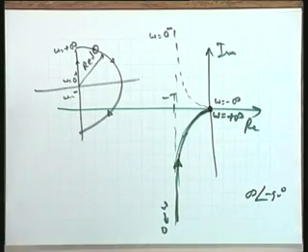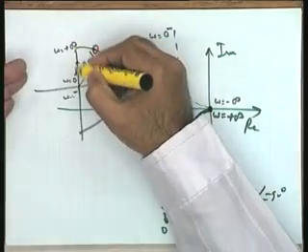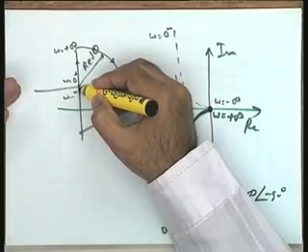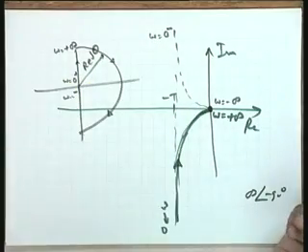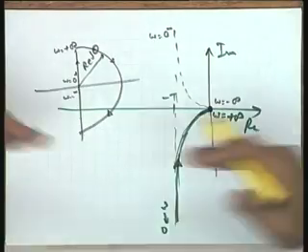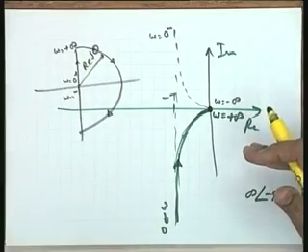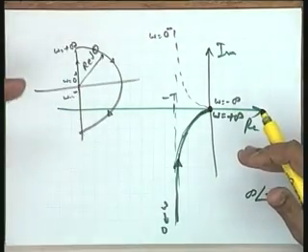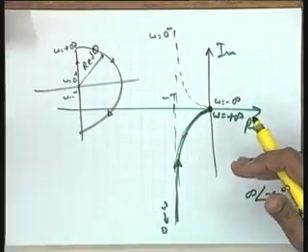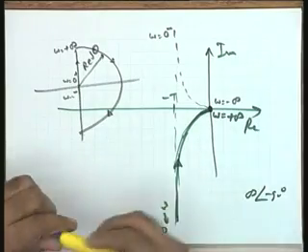Yes, because this plot, you see, this is a general statement I gave, that from omega equal to 0 to infinity and omega equal to minus infinity to 0, any function G(jω)H(jω) is a mirror image of each other with respect to the real axis. So this is a general statement, not particular to this case. It is applicable to any G(jω)H(jω), which can easily be verified mathematically also. Now the only problem in this particular case is the 0 point.